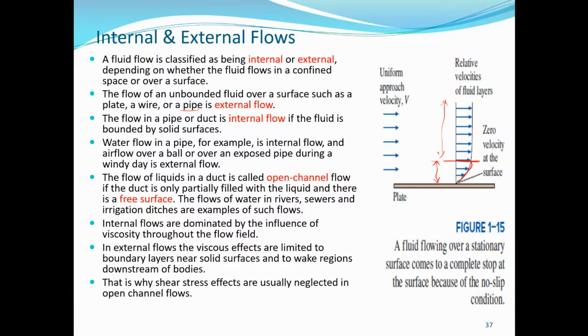And that is why shear stress effects are usually neglected in open channel flows. This I mentioned. For open channel flows, we normally neglect the shear stress effect, because the shear stress effect is limited to just the boundary layer above the solid surface. While for pipe flow, because you have it from above and below, so it is like parabolic, the velocity profile. So the boundary layer becomes more pronounced, and the layer of viscid flow becomes very small compared to open channel flow.